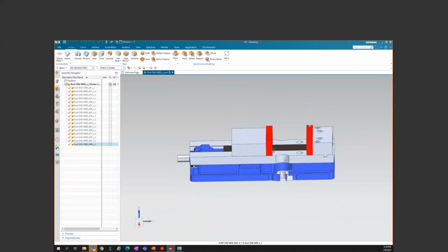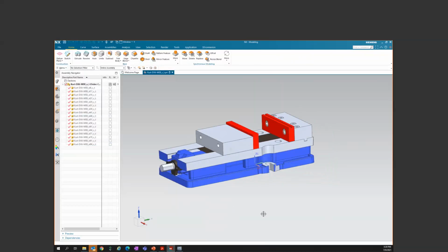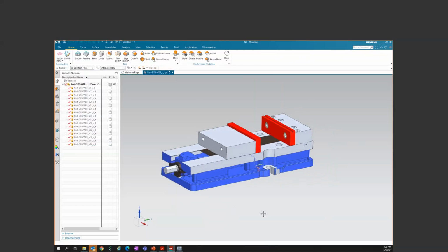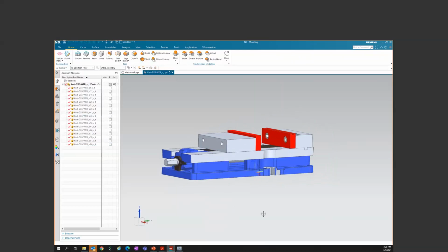So what I did was I staged the adjustable jaw to a set gap distance that I knew I wanted. So I knew my blank was going to be 4 inches. So I already staged this. Originally, when I downloaded this model, this adjustable jaw was way back at the end. But the big trick here, when you want to start to bring them into our software, is you're going to have to export this as an STL. There's all kinds of software out there that can make STLs.